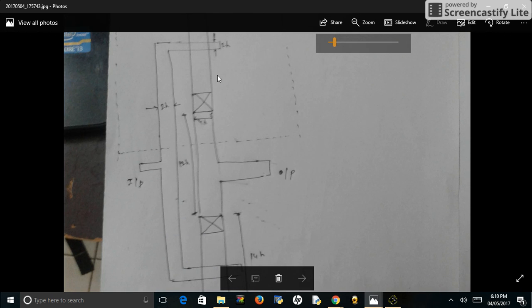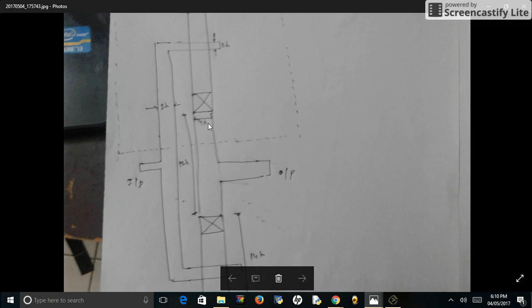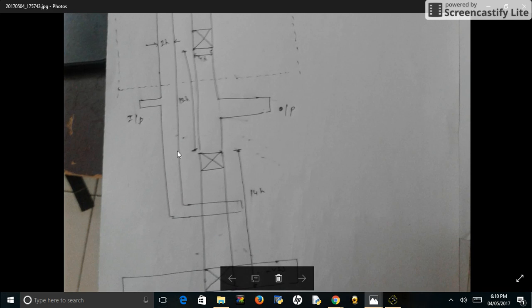Now we connect both gate terminals of PMOS and NMOS by the polysilicon, and here we apply input, and the drains of both PMOS and NMOS are connected by the metal, and we observe output. The minimum width of the polysilicon is 2 lambda, and the height of the polysilicon above the active material is 3 lambda.